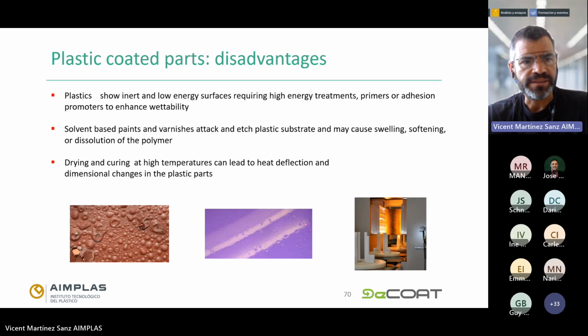Also, these coatings are based on solvent-based paints and varnishes that attack and etch the plastic substrate and might cause swelling, softening, or even dissolution of the polymer substrate. The coating technique's final stage implies drying and curing at high temperatures that could lead to heat deflection and dimensional changes in the finished plastic parts.